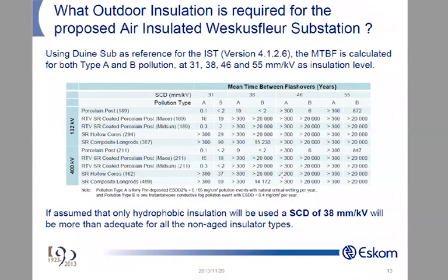But the thing is this, it doesn't mean you have to go and re-insulate and get rid of all your composites, because you've got corona rings on and you've got them correctly installed, and you now need to just monitor and see whether they are okay or not. So never believe a manufacturer or a supplier. Always make certain you double check, and see there is always some agenda which goes along with it.